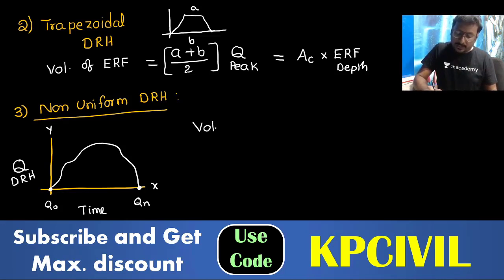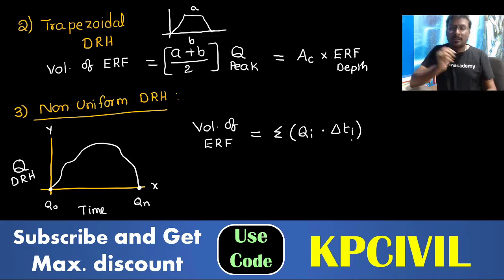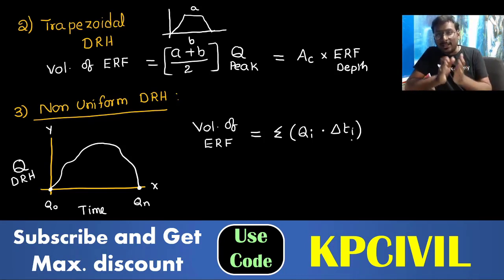Volume of effective rainfall is equal to the area of this one. What is the area of this one? Summation of individual discharges into the time difference delta Ti: Q1 into delta T1 plus Q2 into delta T2 plus Q3 into delta T3 and so on.